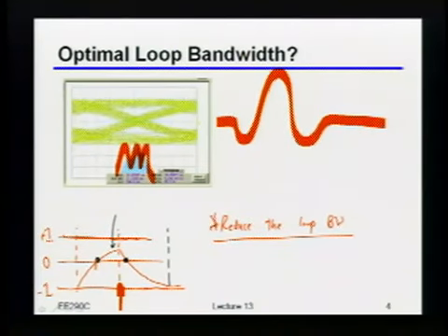Does this kind of make sense to people? By the way, this is a fairly subtle issue that I think most people, including myself, didn't necessarily understand until fairly recently. So what this really means is that, because the edge jitter is essentially uncorrelated with where you really want to put the data sample, your only choice is basically to just filter that jitter out as much as you can.